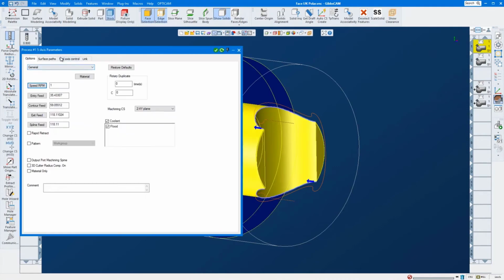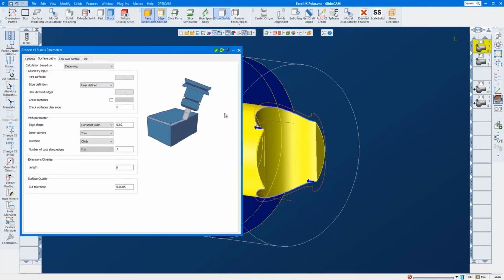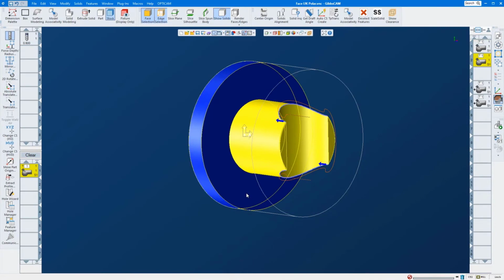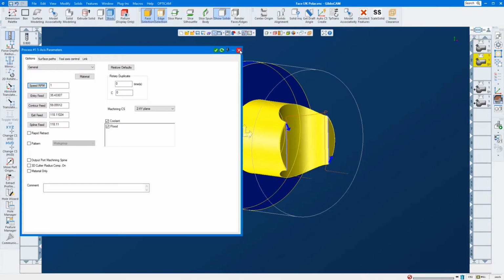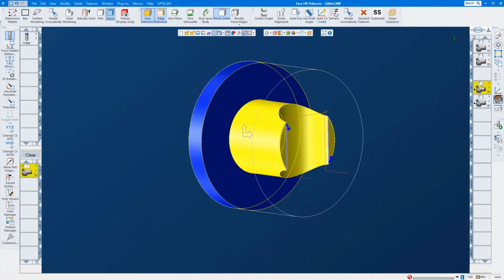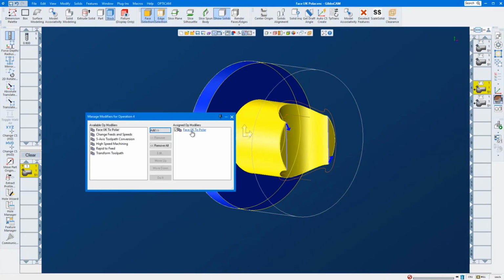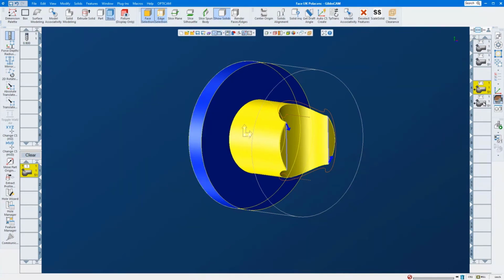So it's straightforward to set up. I just set up a quick deburring op, and actually, I set up 2, so these are just copies of those operations. Just right-click, add that, click do it, and you're good to go.